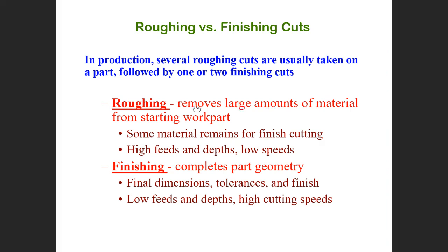In cutting, in machining, we have what we call rough cutting and finishing. Please listen to me carefully, guys. We have what we call rough cutting and we have what we call finishing. In rough cutting, we remove a big amount of material from the starting workpiece. In rough cutting, we use high depths of cut and high feed rate.